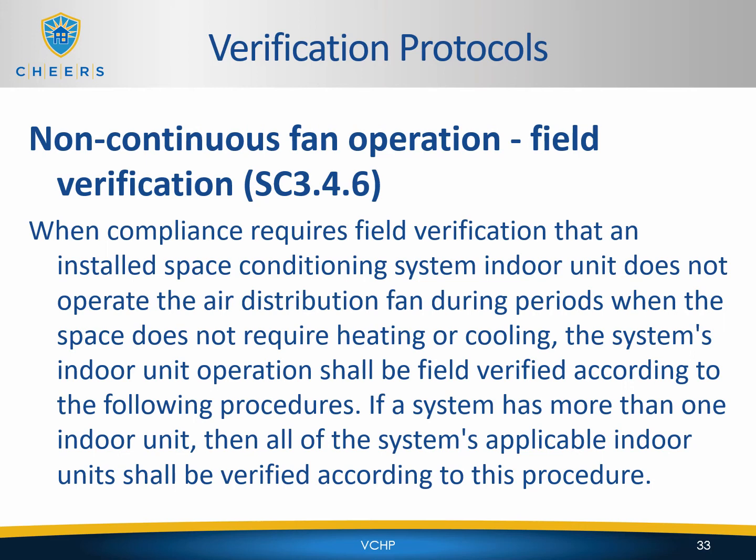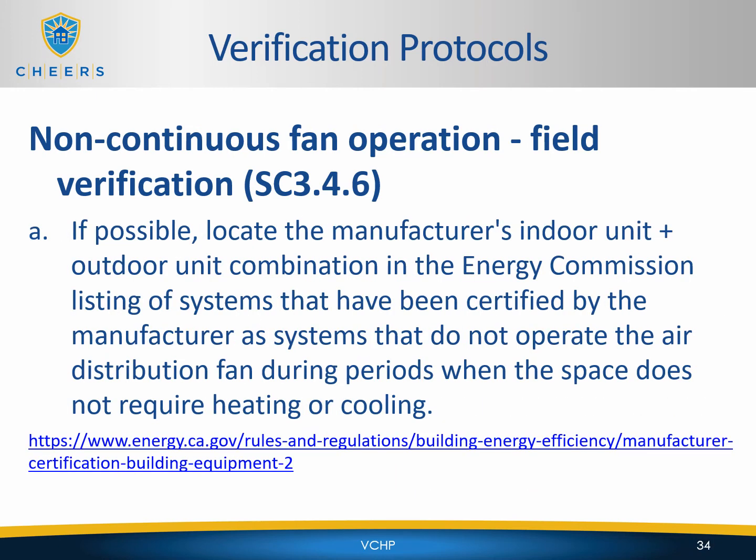If a system has more than one indoor unit, then all of the system's applicable indoor units shall be verified according to this procedure. If possible, locate the manufacturer's indoor unit plus outdoor unit combination in the Energy Commission listing of systems that have been certified by the manufacturer as systems that do not operate the air distribution fan during periods when the space does not require heating or cooling. So this is that same Excel spreadsheet that we looked at earlier with the yes/no column.